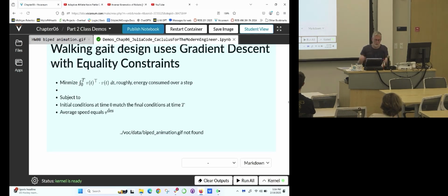And then I may want to add some constraints. One way to use no current is to not move, okay? So if you just minimize current and you don't impose a constraint that I'm going to be walking at least 0.9 meters per second, kind of a standard rate for a human, okay? So that's called a constraint. I set the average velocity. So I minimize torque, sum of torque squared, subject to additional constraints. So your optimization problems are typically constrained.